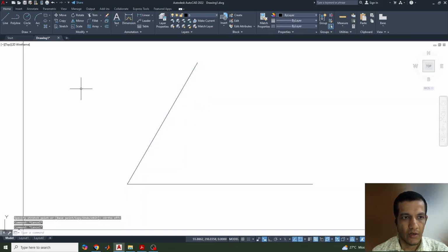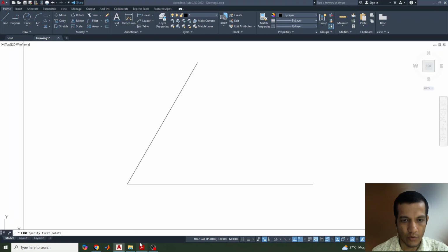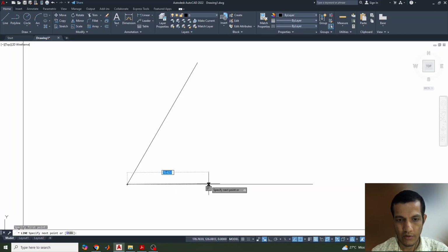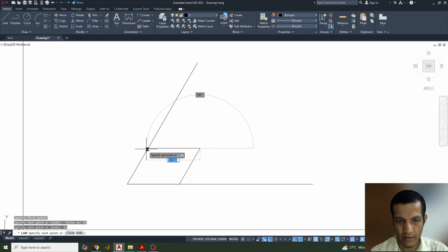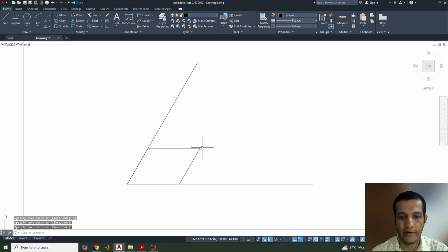And next we have to draw a distance of, I hope, 50 mm. Yeah, 50 and 40. So this is 50 mm. So let's take 50 and a height of 40. So this is a height of 40, again angle 60, and finally on this side we can take 50 and close it here. Okay, so now we got our P point here, and in a similar way we just need to draw two lines which are parallel to the x and y axis.